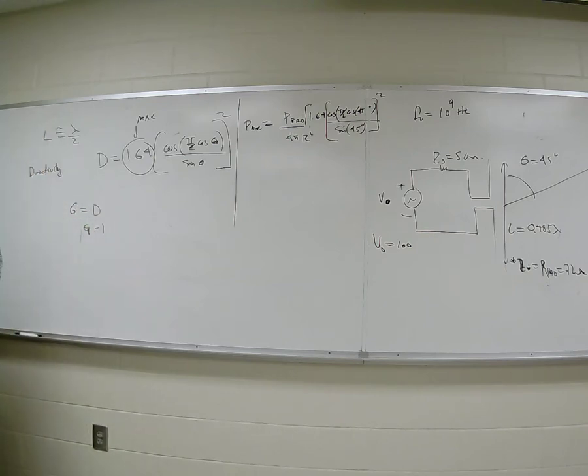I could give you a problem with a certain radius and at a given frequency. You could calculate the resistance of that wire, and we could change the efficiency. For now, I want to focus on the main aspects of this problem, okay? But that's a good point. I'm assuming directivity and gain are the same in this case. The efficiency is normally very close to 1. You never want the directivity and gain to have any significant difference, because then you've got a problem. Usually the standing wave ratio is messed up, and I've had that happen.